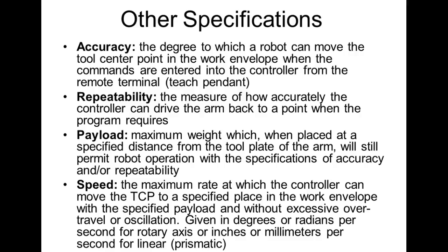So repeatability, what's repeatability? This is how precisely or accurately it will return to the point once it's been taught. So if you taught the point wrong, it's still going to go back to that point, but it's going to have an extremely high degree of what? Repeatability. All these robots are within the nanometers, all the small robots. The big robot is 100 microns.